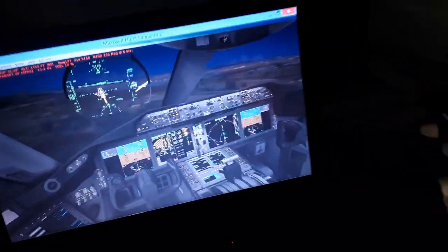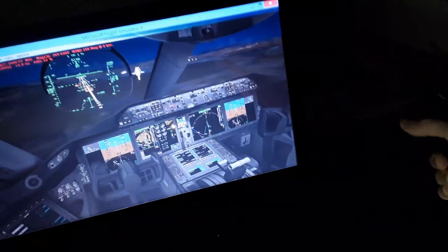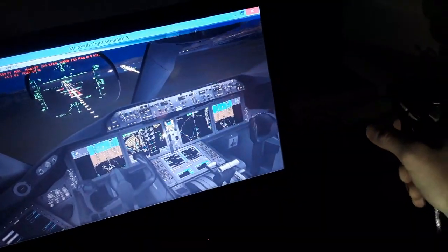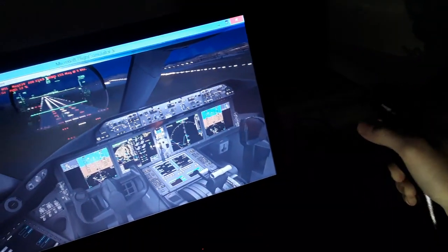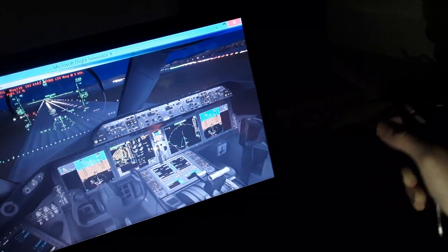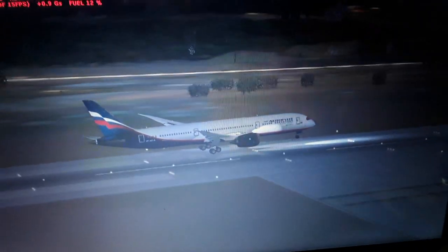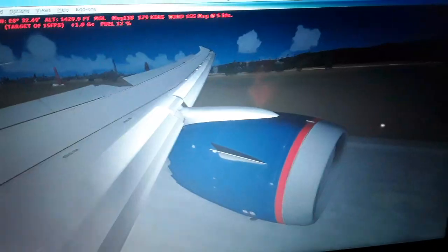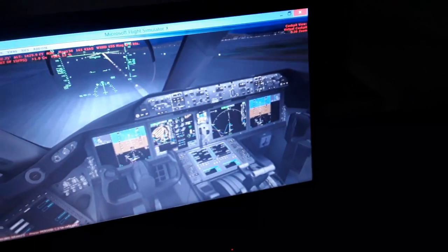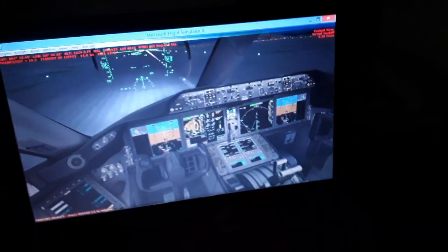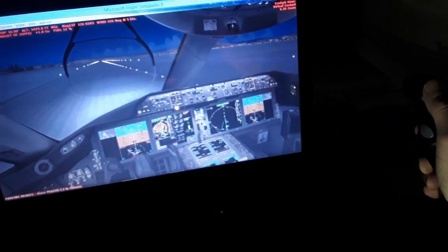So we're gonna touch down in a couple of seconds. As you can see, idle thrust, align again with the runway. So we're gonna be having the flare here. So flare for touchdown over here. Beautiful flare, beautiful touchdown. Align with the rudder pedals over here, parking brakes, and idle thrust. So we have idle thrust reverse, full thrust reverse, and align with the rudder pedals.